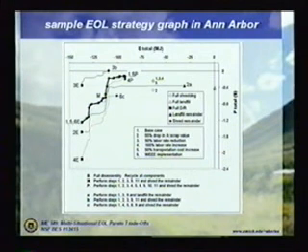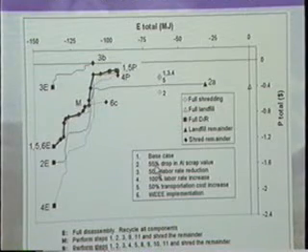But here what you're looking at is the Ann Arbor case. Here is the original case. The base case is number 1. Okay. Looks like local disassembly. Right. Case 2 is a 55% drop in the aluminum scrap value. So we put a 2 next to that. And if that happens, your max profit scenario changes. If you've got a 50% labor rate reduction, that's 3. So you look at curve 3. Right? So you can see that became flatter. 100% labor cost increase, as we saw. You can see that slope becomes bigger.